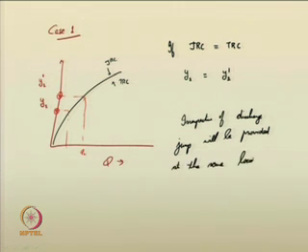Again, this is an ideal situation which is not encountered practically. In practical cases, it is difficult to attain such ideal conditions. So, you need to design it for more practical cases. You may not have the jump rating curve and tailwater rating curve the same every time, so they are very rare.